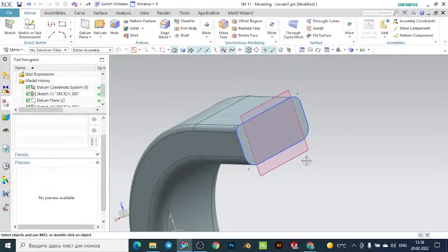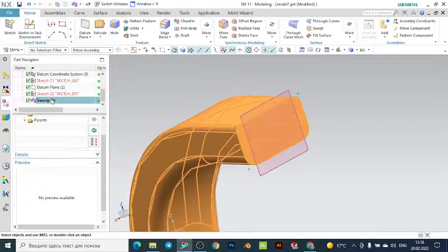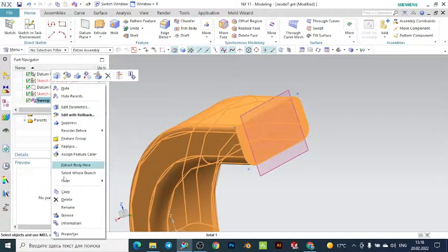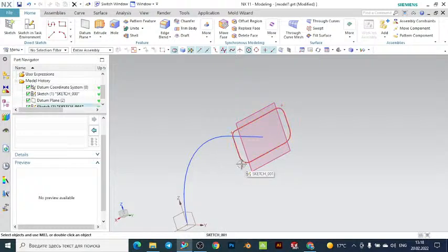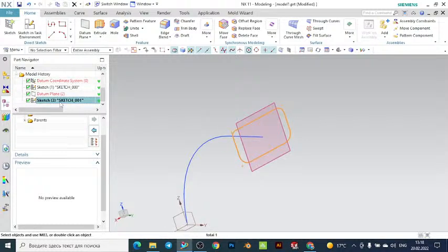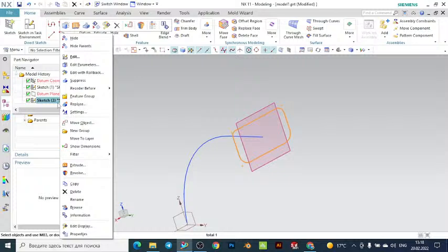So this is how to obtain this kind of element with such a cross section. In this case you can create several such systems with several cross sections. Let's delete this one. For example, instead of this kind of fillets, you can make a chamfer for the corners and so on. And these are just examples of how to create the sweep along the guide with the closed cross section. So let's see some examples with the open cross section.